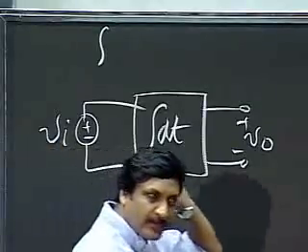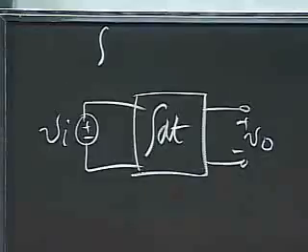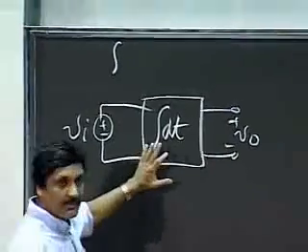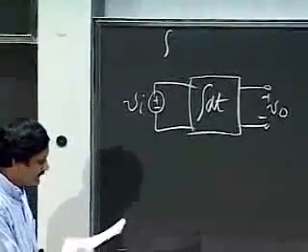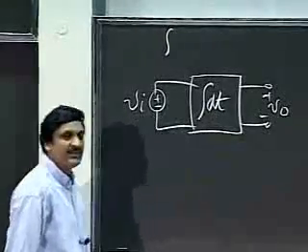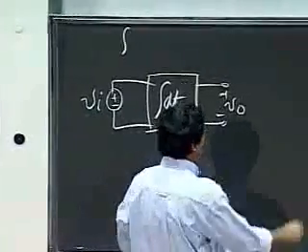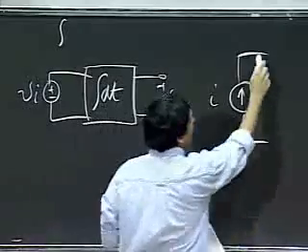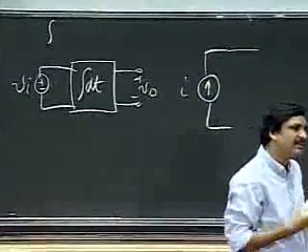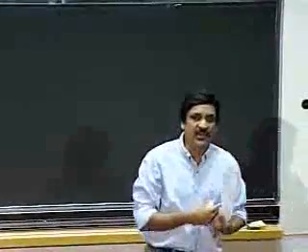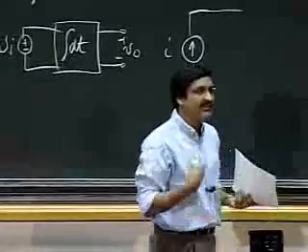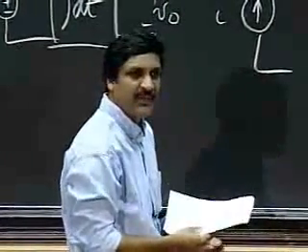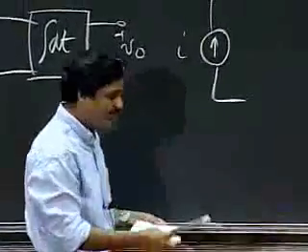So how do I go about building it? What I'd like to do next is give you some flavor for design. Okay, how do you go about designing things with an op amp? Okay, knowing that you do not know the pattern for this yet, how do you go about designing things? Well, let's start with the following intuition. The intuition that I begin with is that if I have a current I, and remember that capacitors and inductors relate to differentiation and integration, as you saw when we dealt with capacitors and inductors. Okay? So I think we have to invoke a capacitor here, or an inductor. In this example, I'll invoke a capacitor.